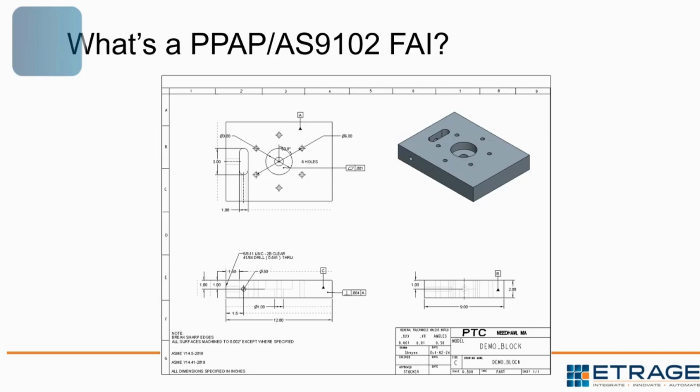And usually, even though it's called first article inspection, it's not literally the first item off the assembly line. It's usually a random sample of the first production batch that is taken, and so a few samples from that batch are taken, and then those are checked.